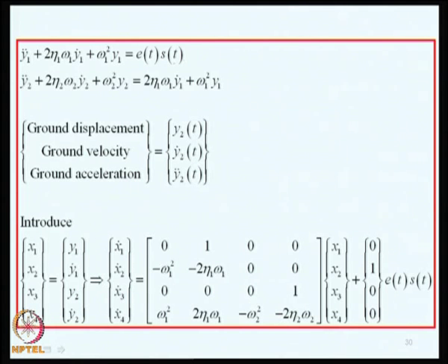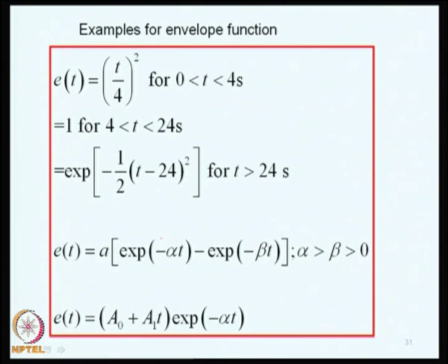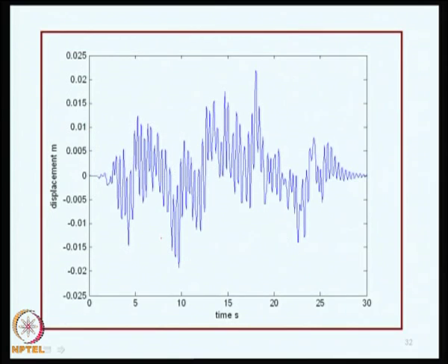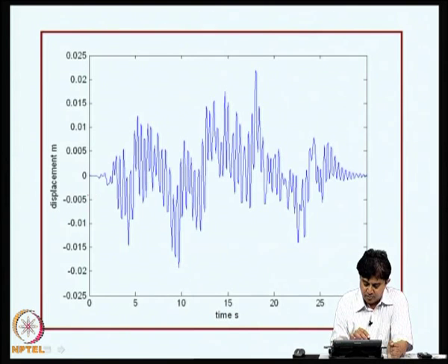What we assume is that at the bedrock level the excitation is modeled as an envelope multiplied by a white noise process. In one of the previous lectures we discussed how this set of differential equations can be interpreted as a set of stochastic differential equations and how we could obtain samples using Ito-Taylor expansion based numerical schemes. Based on that, I showed some of the samples.